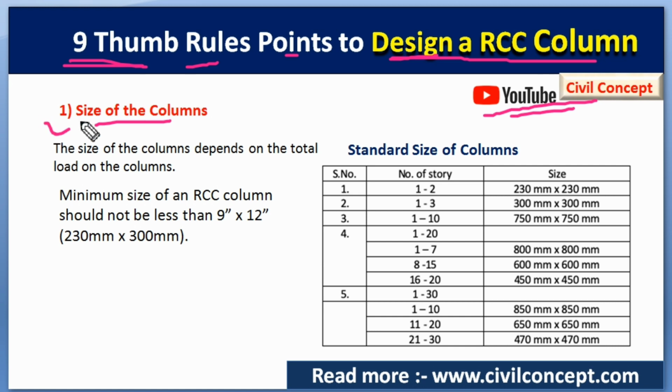So the first point is the size of the column. The size of the column depends on the total load on the column. If we are constructing a number of storeys, then we have to provide the size of the column according to this. The minimum size of an RCC column should not be less than 9 inch by 12 inch. In mm, we have to provide at least 230 mm to 300 mm as the size of the column.